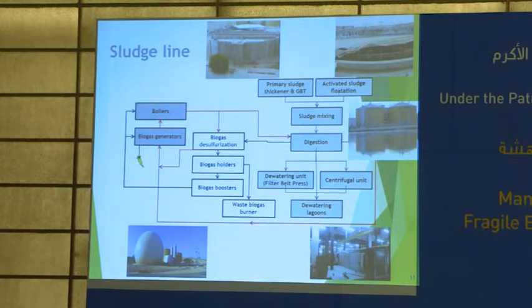The two major structures that produce sludge are the settlers, either in the primary or in the secondary, and then it is sent to digesters under certain conditions to produce methane, which goes to a biogas generator for producing energy. But this is not our issue actually. Our issue is what happens after the sludge is digested. What shall we do with this sludge? I think there shall be techniques to deal with the sludge.